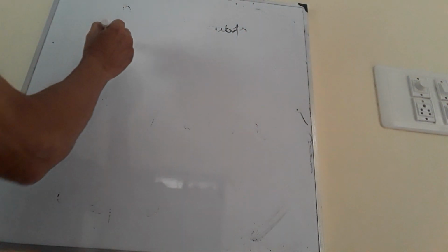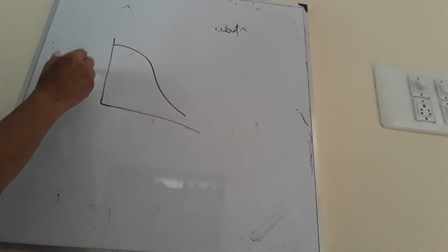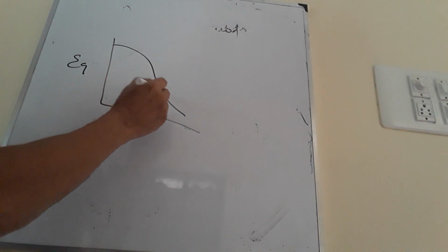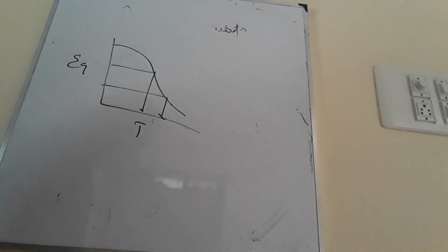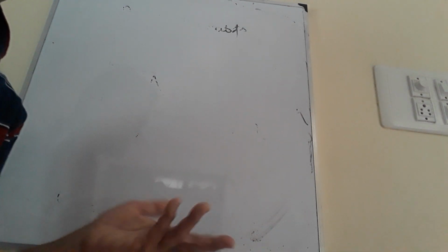And normally most of the reactions in chemical engineering are exothermic in nature. Exothermic means, from the equilibrium composition versus temperature, higher the temperature, lower the conversion. Now, a 5 degree change in temperature in the reactor can change the composition by between 10 and 20%, roughly.